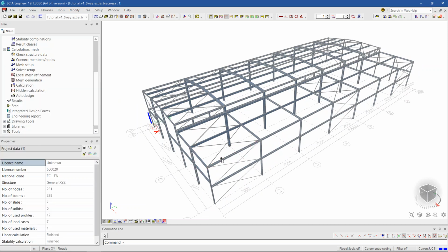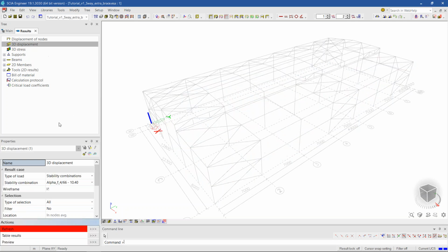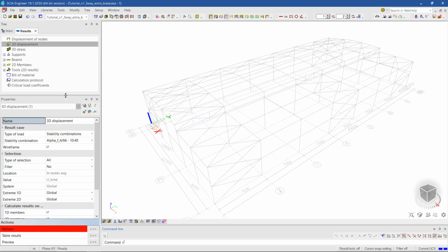And this is why stability analysis is also helpful to tell us how we can improve our structure without having to use very big sections for the members. And so here I had some other modes that I wanted to show you. What was the effect of adding this bracing on the structure? So first of all, that mode that you saw at critical load factor 3 completely disappeared.